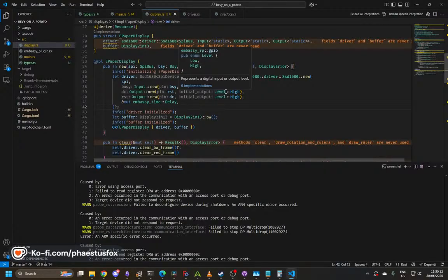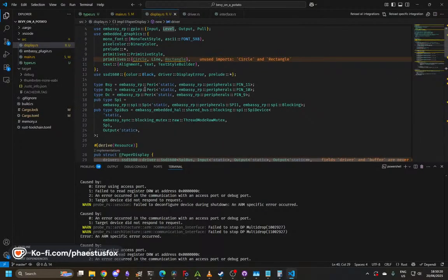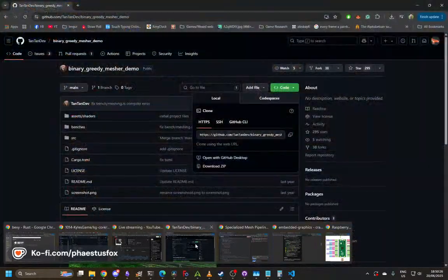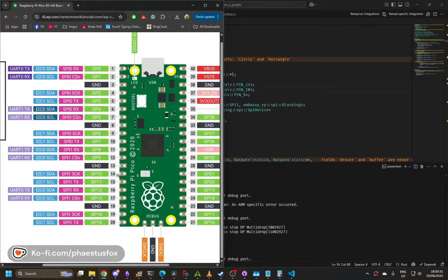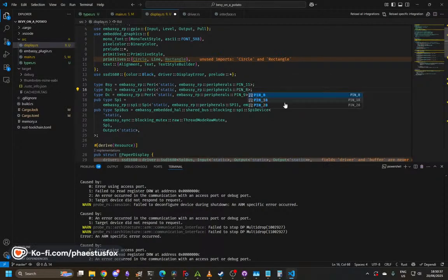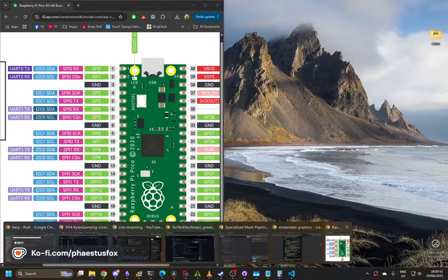Let's try a different pin maybe. Maybe that pin's fried. So let's change reset. Hello, Poisander. So reset's 10. What is another physical pin nearby that I can just plug that into and see? Maybe I've fried that pin at some point. I got it working at one point, so that's interesting. So we're at 10 and we want to go to maybe 8. So pin 8, okay. And then it's going to complain because obviously it's not wired properly. Then we pop you over to physical position 11 on the board. Yes, position 11 is 8.